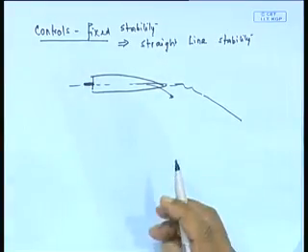Similarly in the ship, which one would you prefer? Obviously, most people will prefer a cycle which has inherent stability, because otherwise you have to continuously monitor it. The same thing applies for a ship. Yes, I could probably make it go straight by applying rudder continuously, but I do not want to. I want to make sure that if I put the rudder straight, it goes on a straight line, and even small waves do not disturb it much. Therefore I am looking for a ship which has straight line stability. If not, I want to study how much it should have.